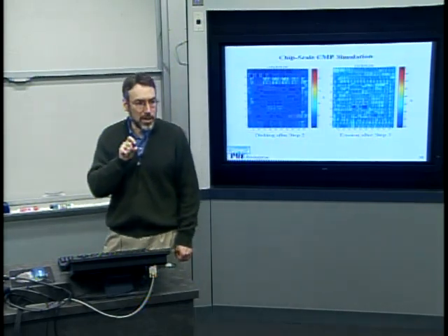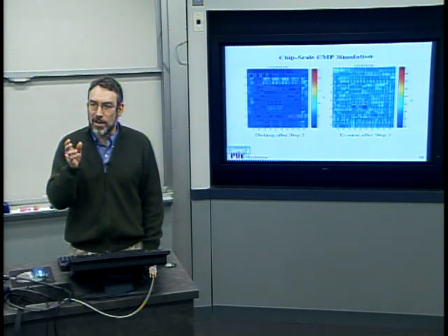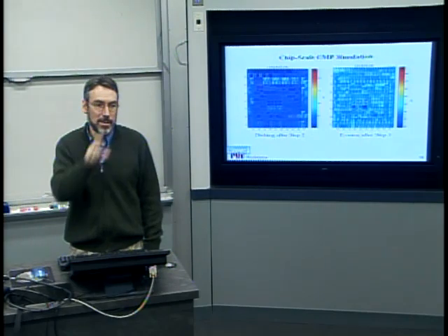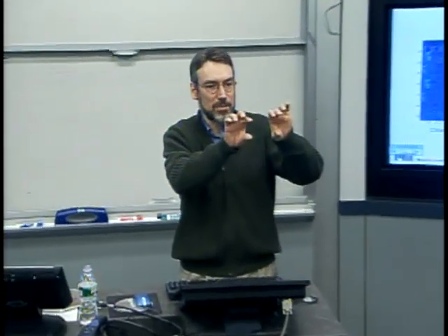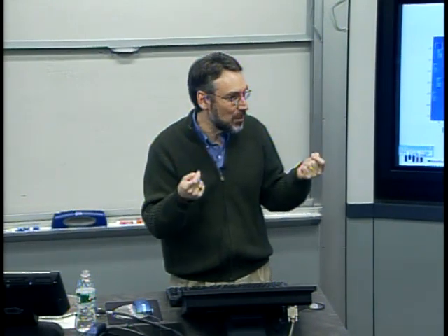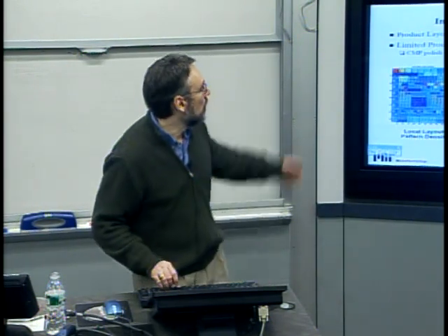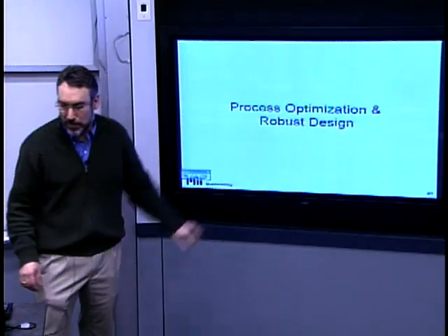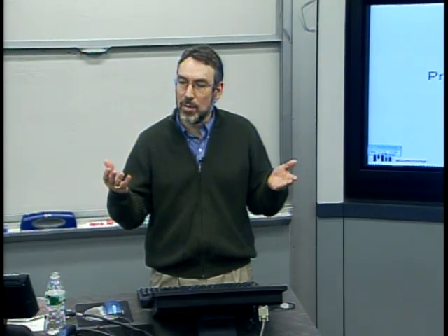And that could be very important because the thickness of a copper wire determines its electrical resistance. It even affects the coupling capacitance between two neighbor wires. So those key electrical parameters, resistance, capacitance, that determine interconnect speed depend on that critically. So that linkage with robust design can be very important. One can also use those kinds of models to play with process parameters and empirically, as a function of the process conditions, minimize these systematic sources of variation.